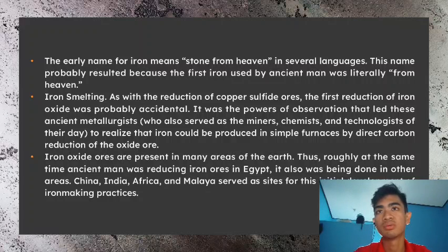The first iron to be developed was wrought iron. Wrought iron can be readily forged to shape. In fact, the term wrought means to shape by hammering or beating. Wrought iron is very ductile for forging because it contains very little carbon. Carbon is an interstitial impurity that strengthens the iron lattice.